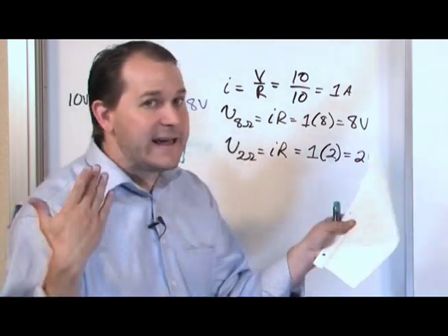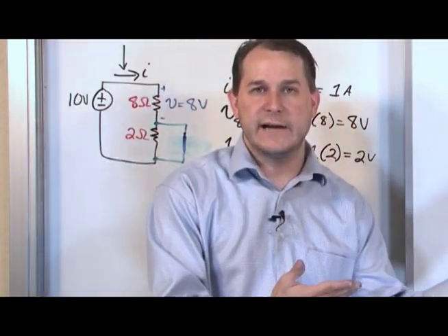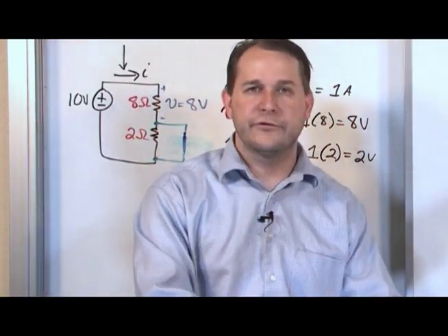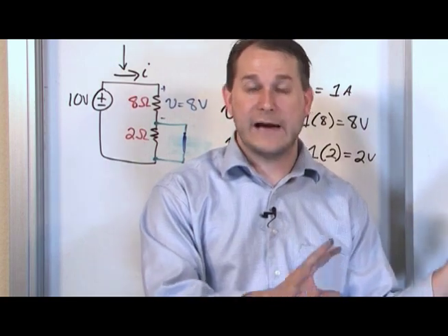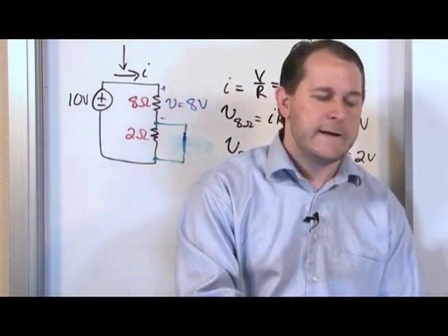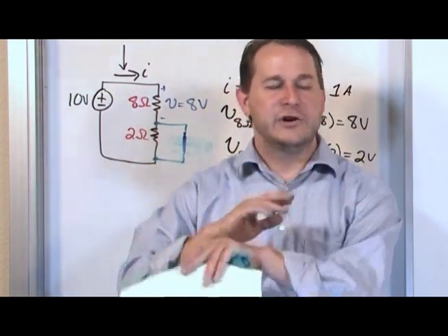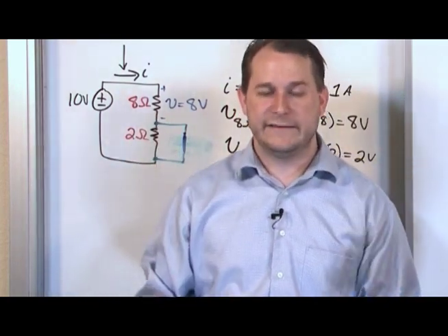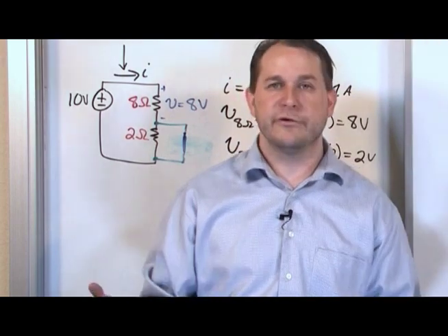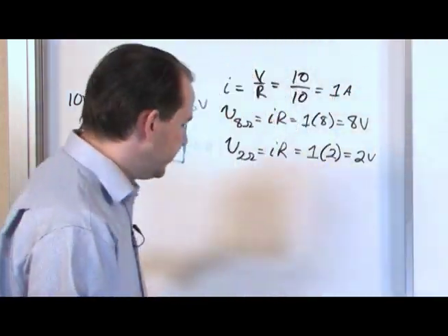So in the limiting cases, with super high resistance connected, it's perfect, you don't alter the circuit very much. You're getting what you calculated as far as your no load voltage. At the other end of the spectrum, you connect zero resistance, a short circuit, and you get no voltage across your output leads, so you've got no usable voltage in your load, basically.